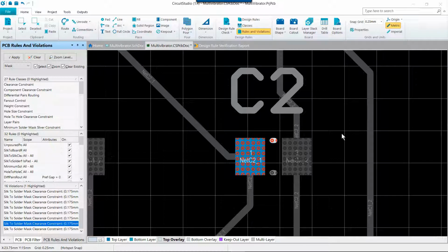There's a lot to show and tell here, mixed in with a few changes we need to make. So to make it easier to read, the exercise is not split out into its own section here. As the designer, you have to work out the most appropriate way of resolving each design rule violation. There are two ways of resolving the clearance constraint between the pads in Q1 and Q2. We can either decrease the size of the transistor footprint pads to increase the clearance between the pads, or we can configure the rules to allow a smaller clearance between the transistor footprint pads.